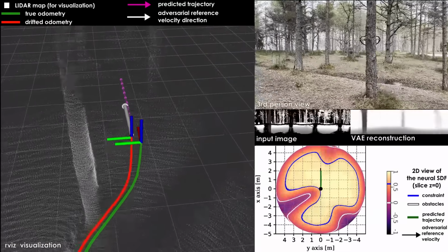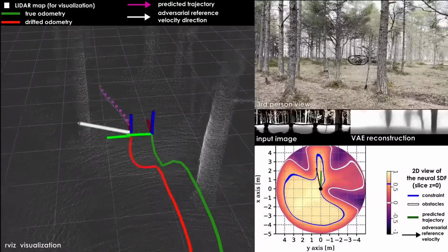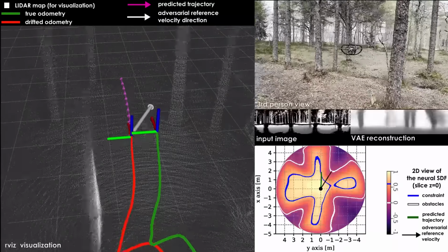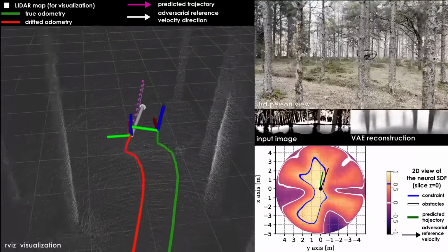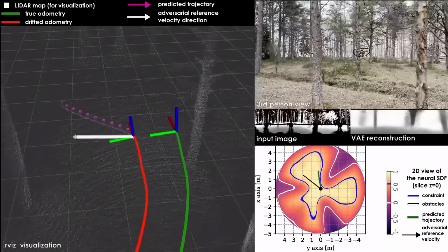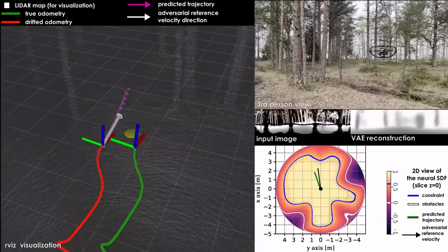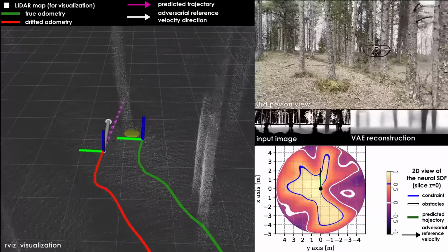We use the 360-degree LiDAR for collision avoidance and use the FMCW radar and IMU for velocity estimation. The system position is retrieved through integration and therefore drifts, with a relative position error of around 3%. The green odometry represents the true position in the map as computed from the LiDAR data for visualization purposes. The red one is the drifting radar odometry provided as an input to the nonlinear NPC.